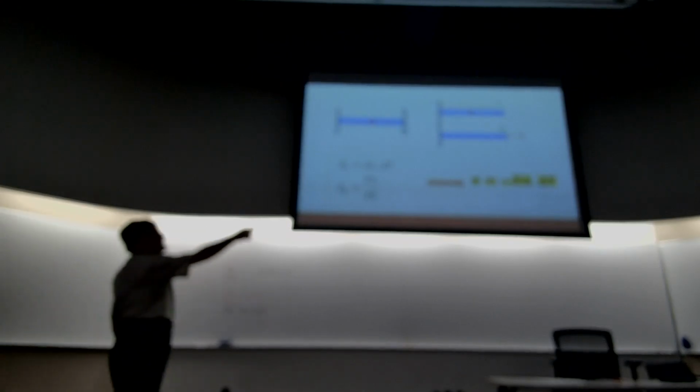So what I have is sigma divided by E is equal to minus alpha delta T, or sigma is minus E alpha delta T. So this is the stress induced in the material because of the temperature rise, and that has been highlighted in yellow on the slide.